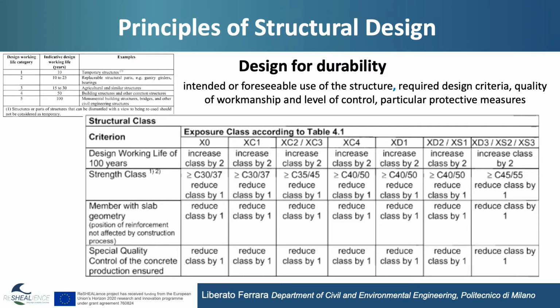And then you can see that not only depending on the stress class, but also depending on the service life that you want to assume, depending on the quality control measures that you put into practice in the construction, depending on the structural geometry, you may play with the classes going for more strict or more relaxed requirements.